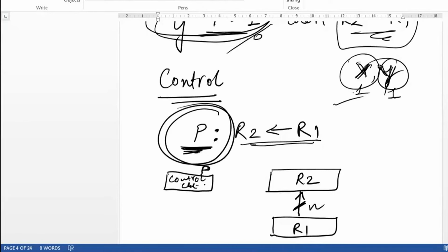Okay, its name is P. Can anyone tell me what will I do over here to the control function? Where will I connect it? I will connect it to the load of R2 register. You all know the purpose of load. We have already studied it in digital system, that every register has a load bit assigned to it. And what will this load do? Only if the value of load is 1, data gets transferred. So can I connect this P to the load over here? Yes or no? Right. So only if the value of P is 1, my data would get loaded to my register R2.